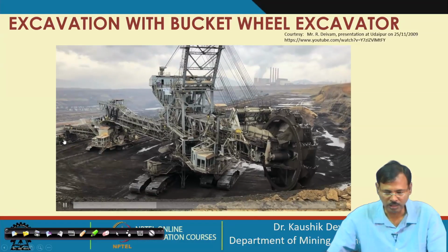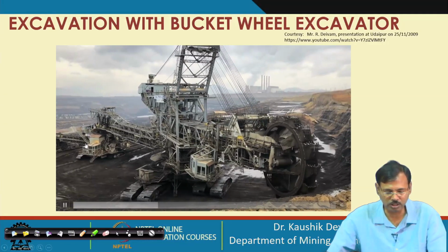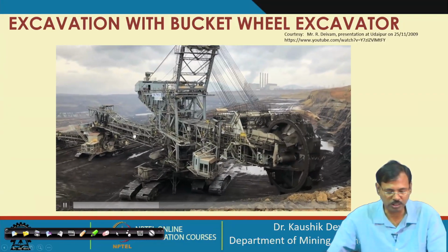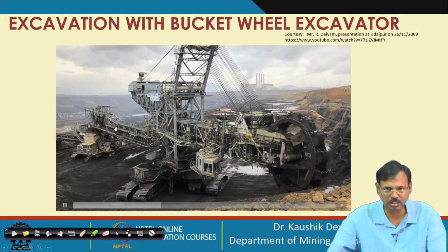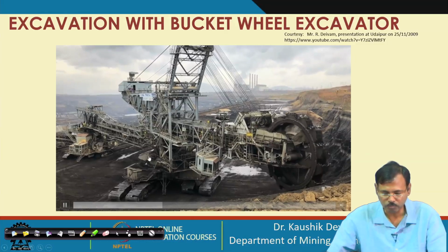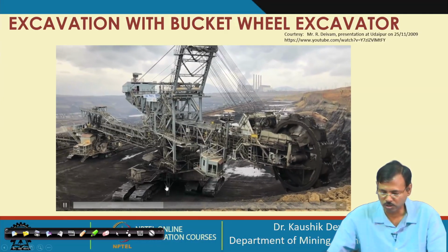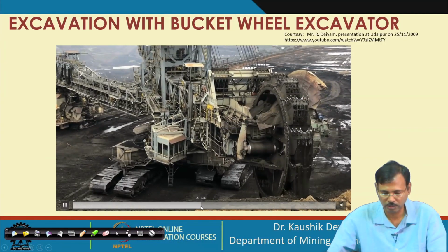The frequent transfer of the shiftable conveyor is not required if some intermediate conveying system, in terms of a bridge conveyor or a mobile transport conveyor, is available in this case. So, this is in a nutshell how the bucket wheel excavator is operating.